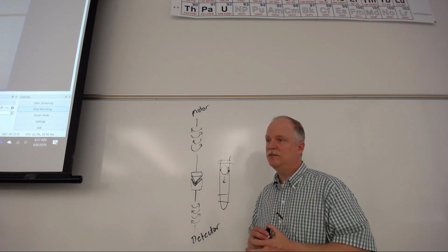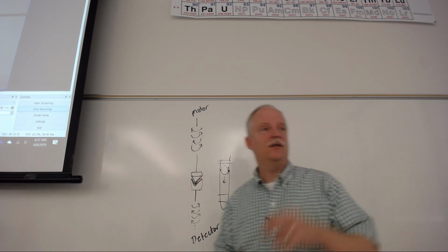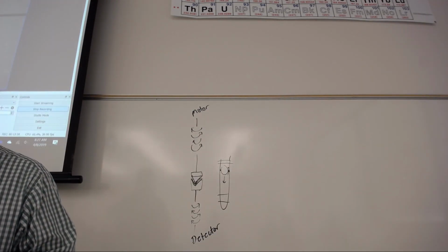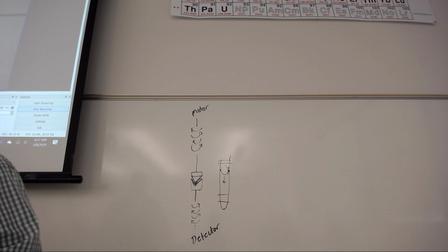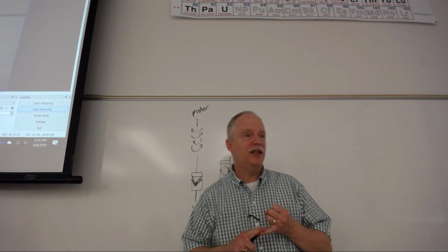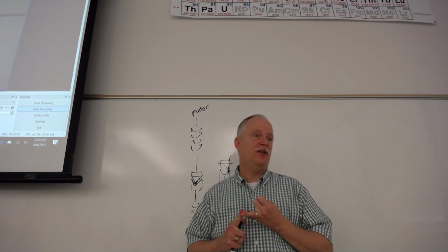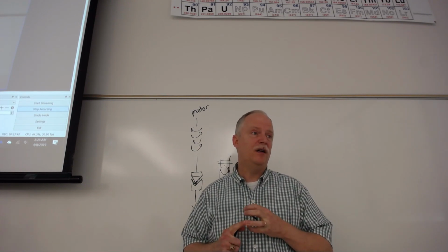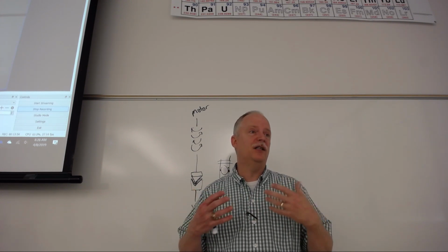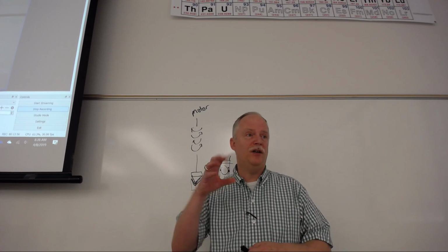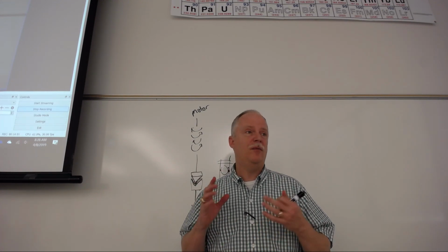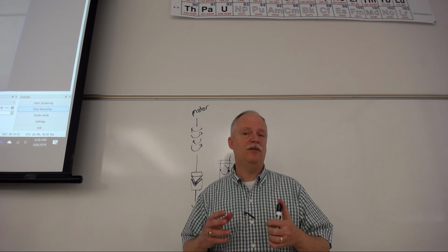Yeah. So, it seems like the ball, wouldn't that be more related to density of the material that it's in? Yes, and so we're going to do that. This is this week's lab. So you need to know the density of the ball, and you need to know the density of the fluid. Okay, and so you have both of those factors in there, and they're in the equation. You pull those out, and then you get the viscosity differences. So yes, the density of the fluid is part of this, and so is density of the ball.